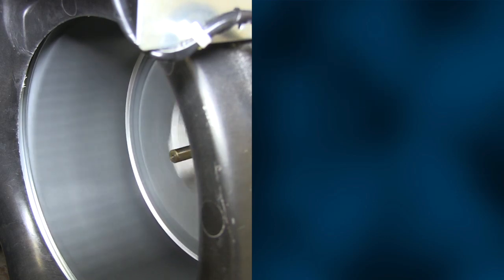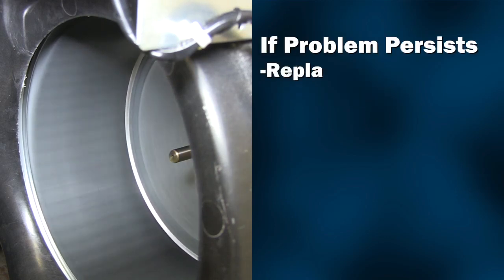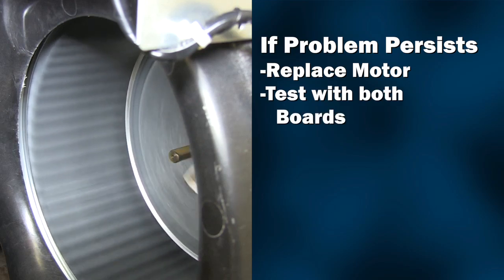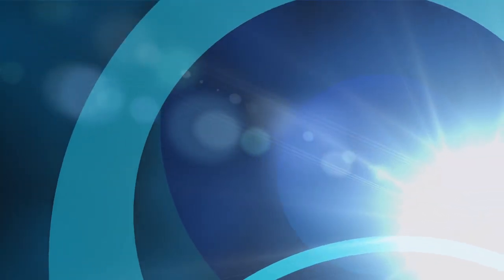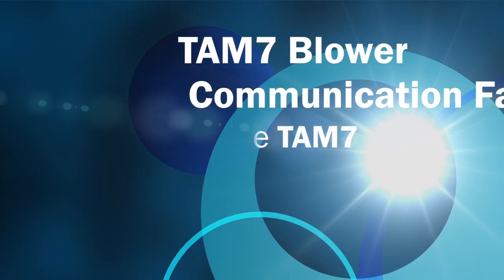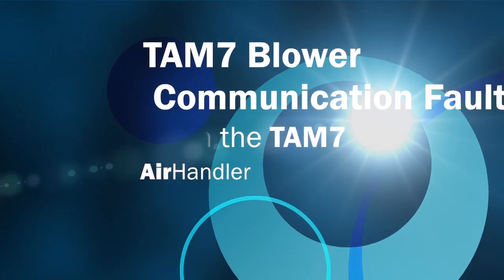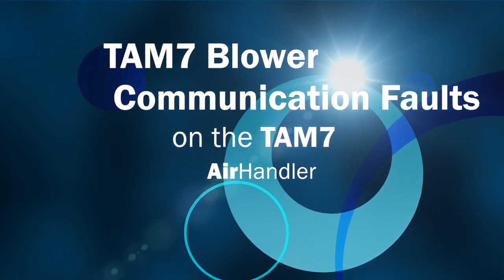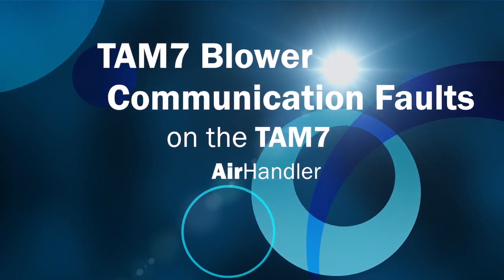If the problem persists, install a new blower motor and test it both with the old AFC board and the replacement AFC board. This concludes this demonstration of troubleshooting TAM7 blower communication faults. Please refer to other FieldTechHelp.com videos as well as TAM7 technical documentation for more information and additional troubleshooting procedures.